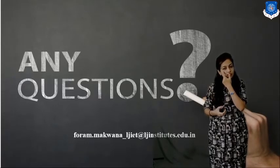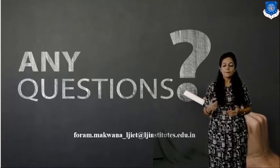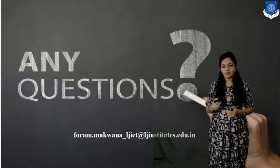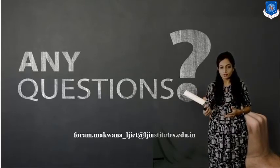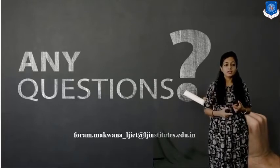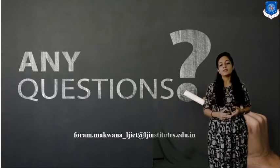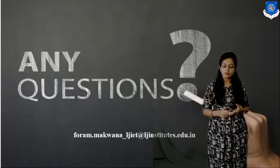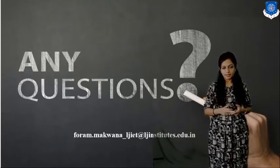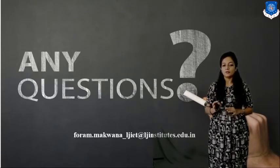The sum signal is used for range information and the difference signal is used for the angle information, alright? Apart from that, we have seen the comparison between the amplitude comparison monopulse and the phase comparison monopulse, right? Which one is better? That we have discussed in chapter number 5.